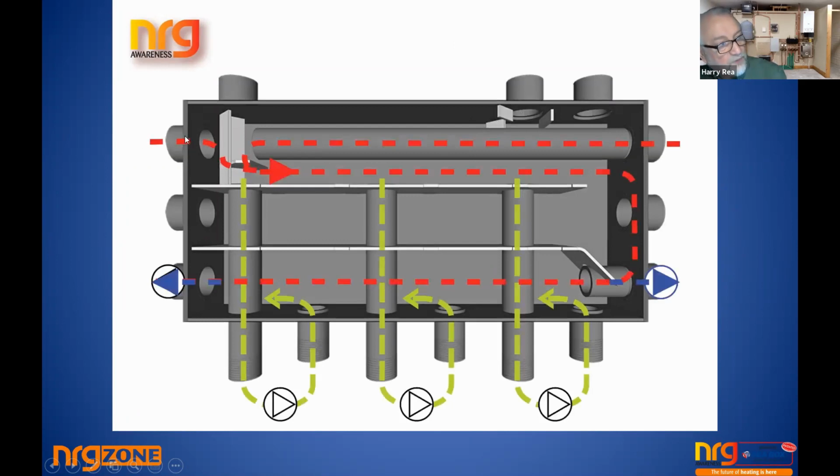And you can see here that if a flow comes in from here, it could travel along and go down. It could go out here, or it could travel along passing the zones and go out here. It could go out any one of those returns. If the boiler comes in from this side, it doesn't conflict with the other boiler. There's no need for any extraordinary devices. It just travels along, turns back on itself, and so again presents itself to each of the zones down through the neutral point, where every pump on this system, whether it's a boiler pump or a zone pump, is pulling water in from a pipe. Let's call this square area a pipe, and this is a pipe. That pipe has an opening here, and it has an opening here. This is the neutral point.